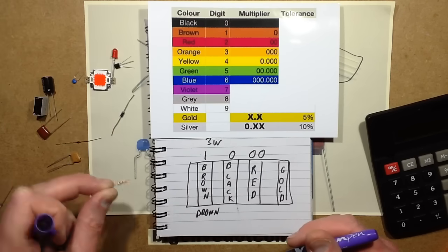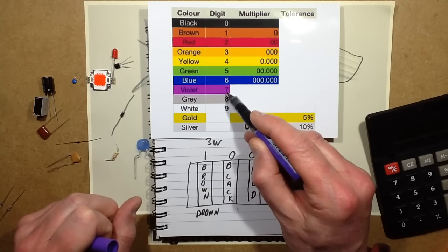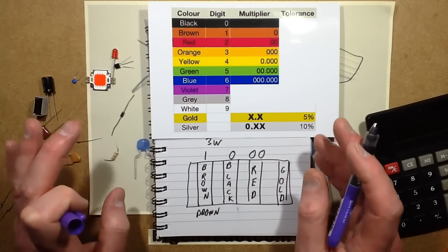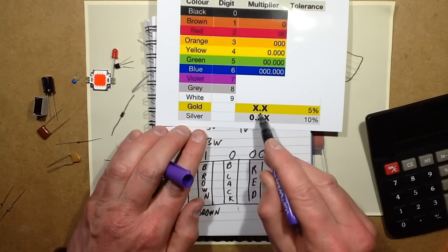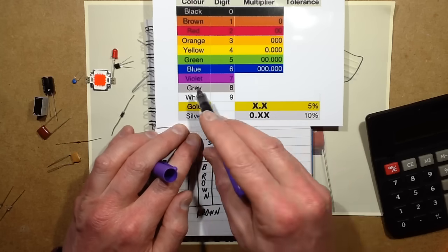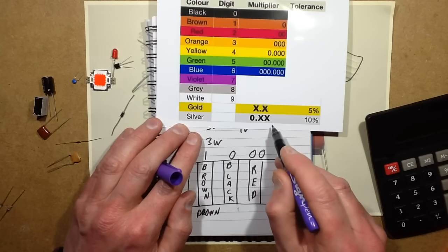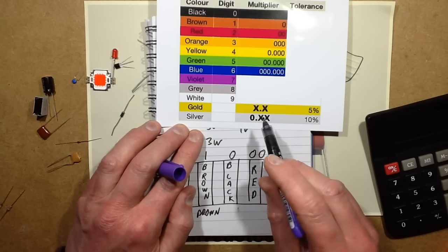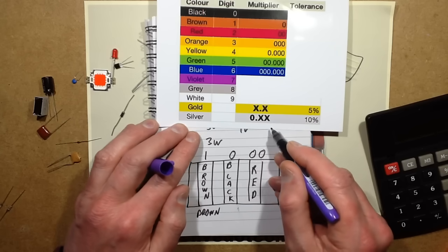If you had a 47 ohm resistor, it would be yellow for the 4, violet for the 7, and then because there are no zeros after that, it would be a black band. Yellow, violet, black would be 47 ohms. If it's going to be a much lower value, like 4.7 ohms, you'll get basically a divider, either gold or silver. If it's followed by a gold band, it'll be first digit, point, second digit. So for instance, 4.7 would be yellow, violet, gold. Or for even lower values, I can't say I really come across silver often, it's 0 point and then the first two bands. So in the case of the 4 and 7, the yellow and violet, it would be 0.47 ohms, a very small value.